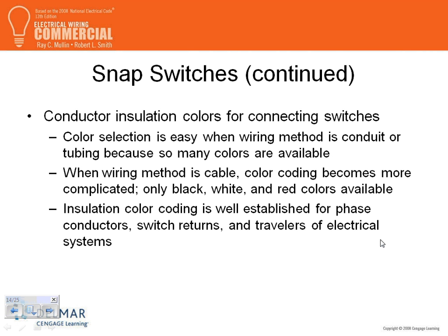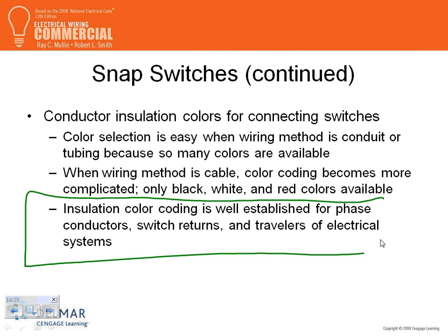Conductor installation, color for connection. Okay, so when we have the switches, usually you have a black and white. If you have a conduit system, you can pull any color you want. With switches, we can identify the switch return. This is what I want to emphasize. If you are wiring with boxes, here's my box, here's my conduit, and here's my light.